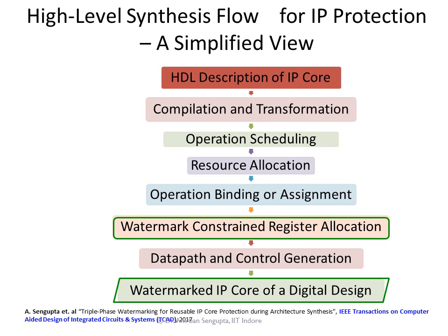So for DSP cores or DSP hardware, implanting a watermark is best, or optimal, during the high-level synthesis design process, because we are starting to design the DSP hardware right from the beginning of the abstraction level.